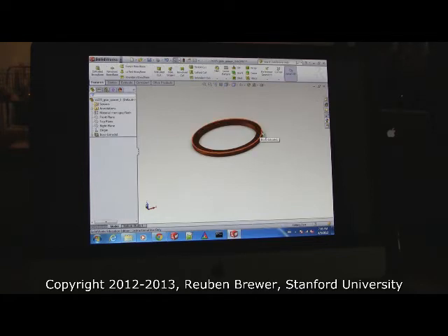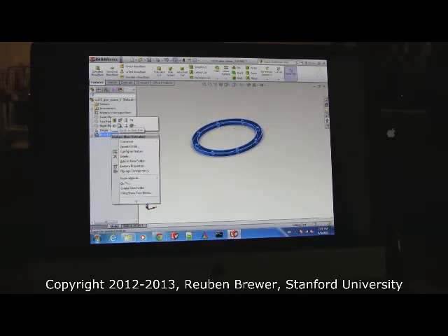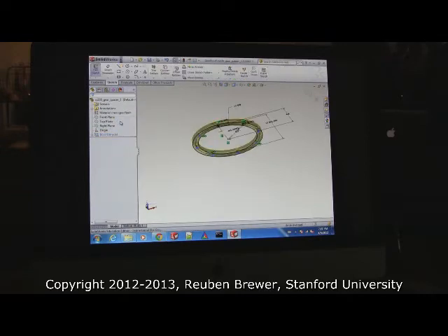Say we decided we screwed up the diameter, we need to modify it. The way you modify a sketch is you click on the Boss-Extrude, right click, you see this little button, look at my screen, Edit Sketch, click Edit Sketch. Now, it's kind of hard to see, right, on my screen, it's still at a weird angle.